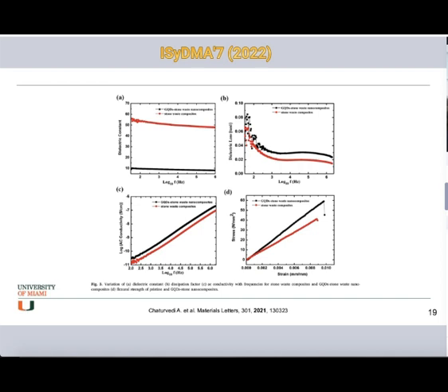The increase in AC conductivity with frequency is attributed to the pumping force of the applied frequency, which helps in transferring the charge carriers between the different localized states in the stone epoxy matrix, as well as liberating the trapped charge from the different trapping centers in the carbon dot stone composite.